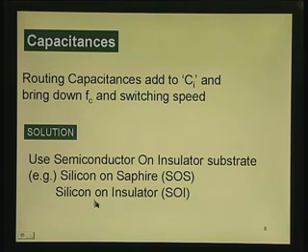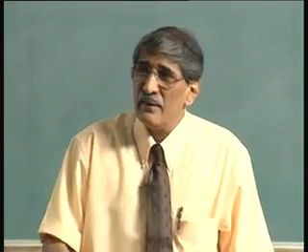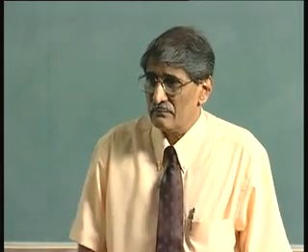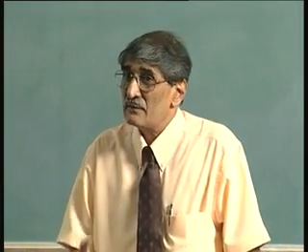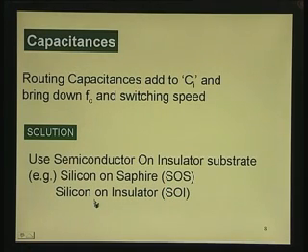Materials like gallium arsenide themselves can be very high resistivity materials. You call it as semi insulating material. Instead of insulating material, semi insulating. Insulator will have resistivity of about 10 to the power 13, 10 to the power 14 ohm centimeter. Semi insulating material will have about 10 to the power 10, 10 to the power 9, which is much higher compared to a semiconductor. So, those concepts, in fact, I am just giving you only a flavor today on this. More about this we will have occasion to discuss.